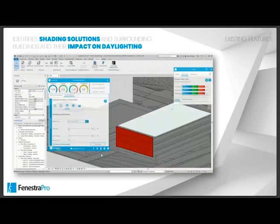With shading solutions, we can understand the implication on those energy performance parameters very quickly in a conceptual mass, but also in a more detailed model. Say if I have a 4-foot deep shading device, my solar heat gains will be much more manageable, but my daylighting will be reduced far too much. So very quickly, very intuitively, we can get an understanding of that.